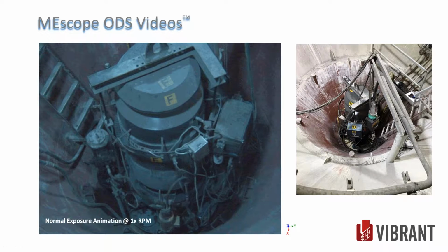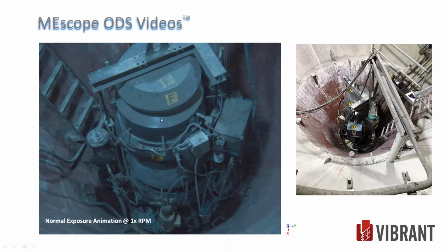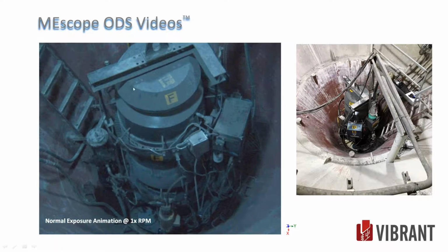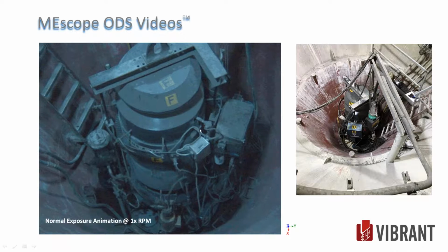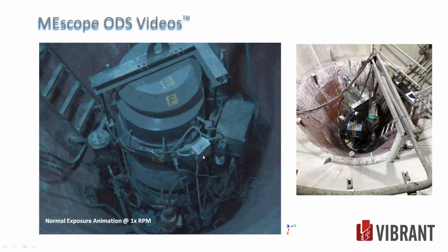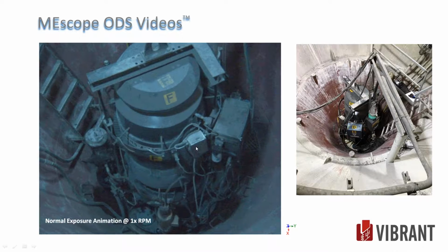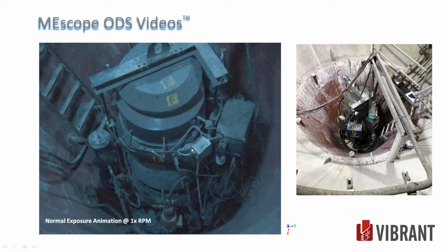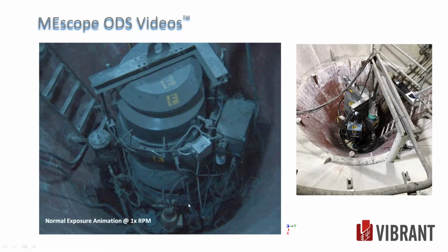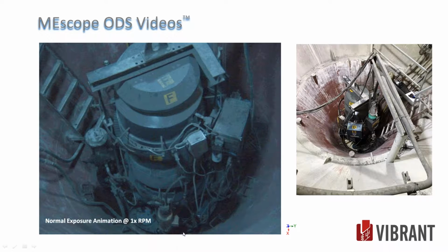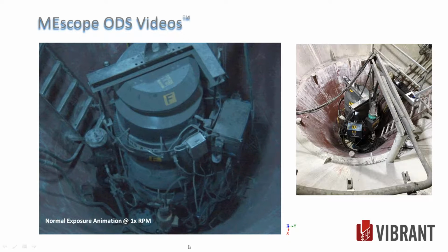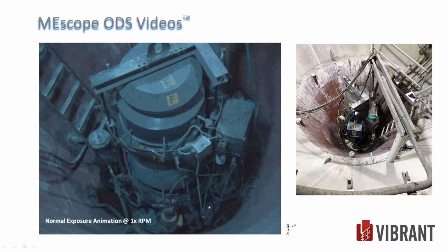This is 1 times RPM. So this is the little bit of whirl in this machine, and as it's spinning, this has a lot of motion. Actually, the animation would have looked better if this box wasn't in there, because it has to rescale the response so much to see it. This box had a poor mount, electrical box, and is just swinging around. There's something else down here. One of the cables that was running down to the bottom was resonant, or moving quite a bit at this frequency.